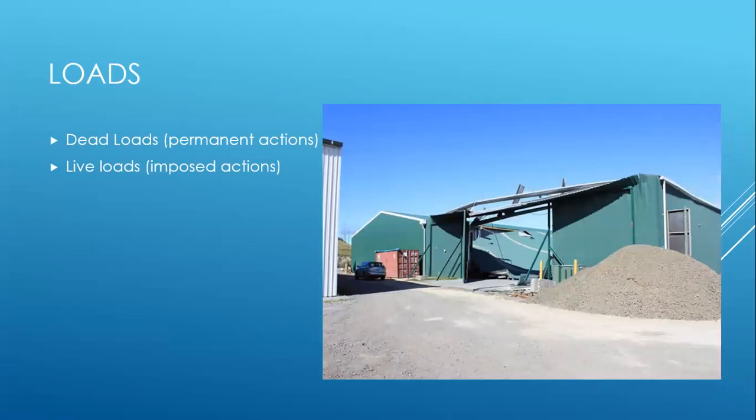Loads or actions are the forces imposed upon a structure. Loads must be known so that the structure can be designed to withstand and perform while subjected to these loads. Loads or actions can be broadly categorized into dead loads or permanent actions, and live loads, variable or imposed actions.